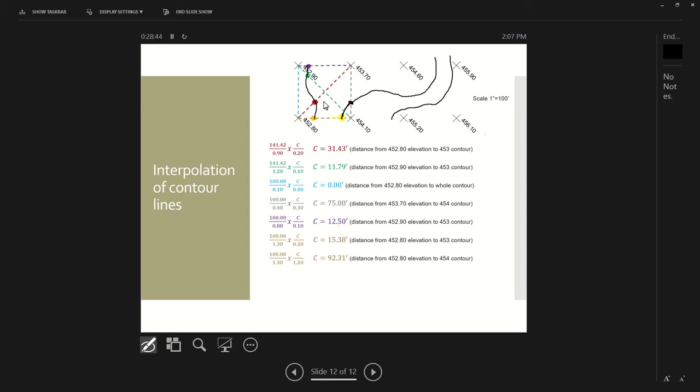So you're going to have to do this to make crosses all the way across that whole sheet of paper and draw these all in. So I'd be cautious when you do the assignment to sketch. If you do these lines in there so that you can figure out where you're putting your point, draw them in really light, because when you go to do the contours, if the crossing lines are dark, you won't be able to see your contours really well, okay? So this is how you'll have to figure out your contour lines, your points of elevation.